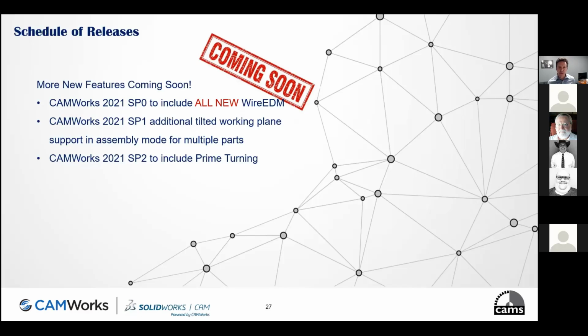Some of you may be familiar with prime turning. It's invented by a very famous tooling company. We're not quite yet sure if we're allowed to share that or not, but it's a really unique way of turning and taking off additional material very quickly, while utilizing the tool geometry for chip thinning and still maintaining optimum tool geometry for getting into those 90-degree corners and such. So something to look forward to.